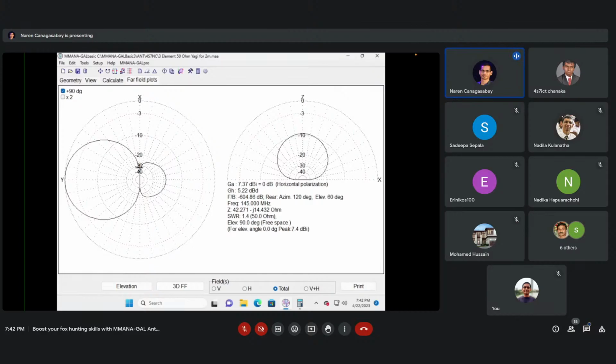If you remember, the dipole had a lobe of the same size on both sides. You can see that by the addition of the driven element, the reflector and the director, the back lobe has got smaller. And you can see the gain, 7.4 dBi, perpendicular to the antenna, and how it reduces as you move to the edges.